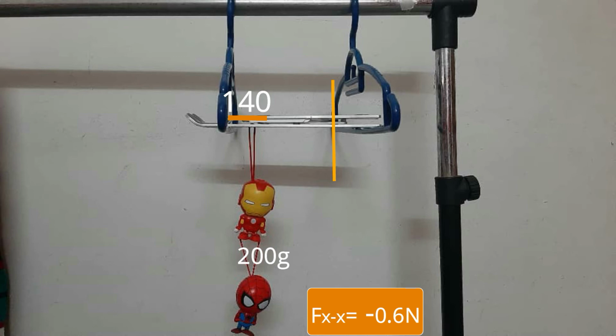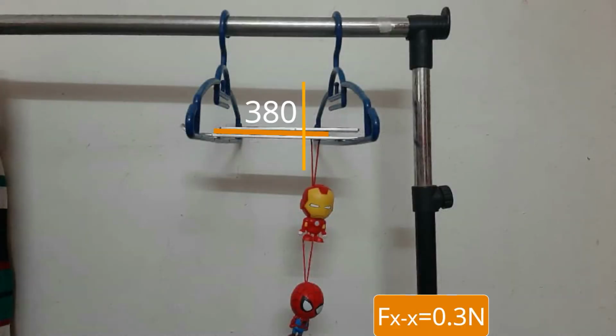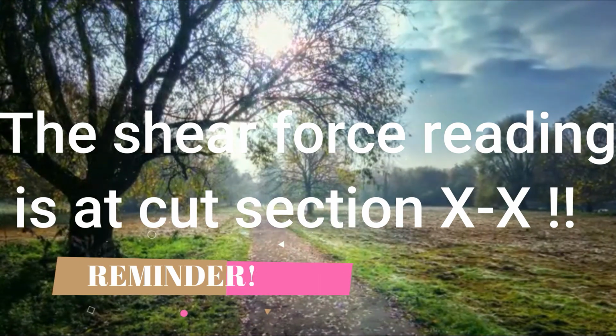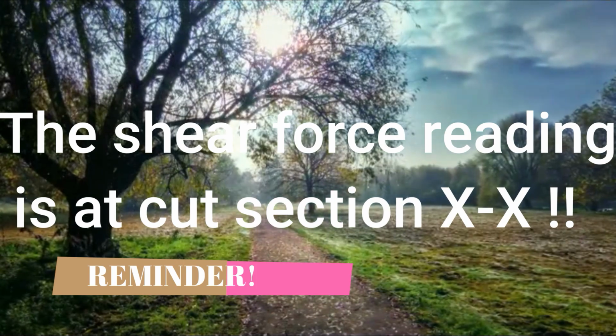-0.6 Newton is recorded. The negative symbol in the display shows that the shear force is acting in opposite direction of the usual shear force. Lastly, the 200 gram load is placed at position P3, 380 mm away at the right of support B. 0.3 Newton shear force is observed. Please remember, the shear force recorded is at cut section XX.